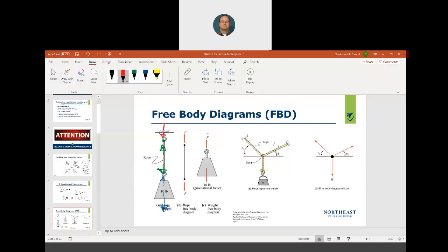So these ropes. So this is a point of common concurrency right here. Okay. You notice these ropes are in tension, right? Hence, we assume we're pointing away from the point of application, or they call that a node. Okay. So that's a point. So the trick to these free body diagrams, can you find a point of common concurrency? Yes, right there. Boom. Here it is.